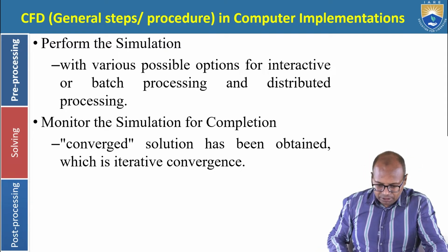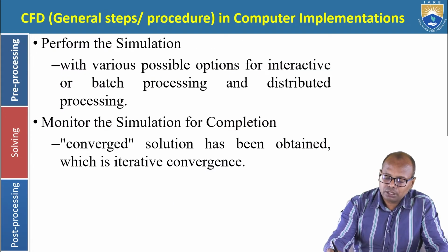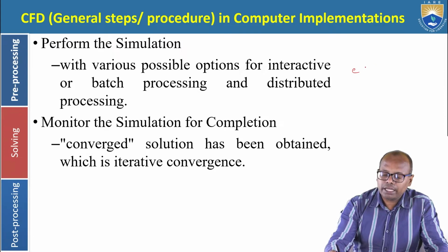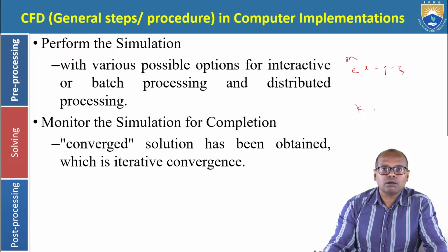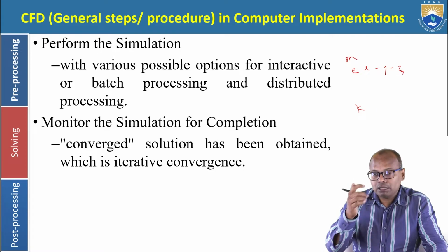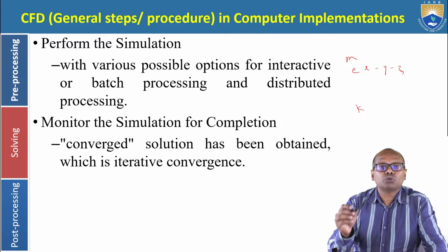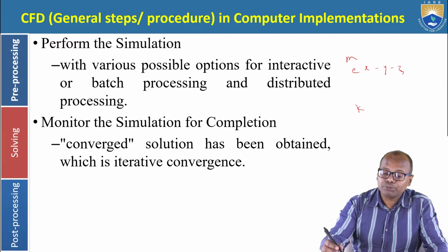So what is the convergence criteria? We have x momentum, y momentum, z momentum, and mass and energy. All these values must be simulated to a certain acceptable error.